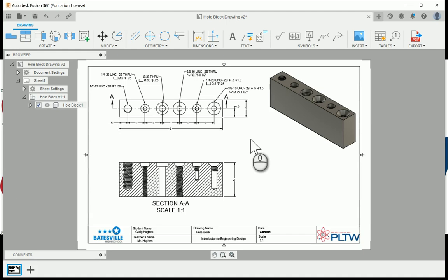In this video we're going to explore how to add tolerances to drawings in Fusion, and we're going to do that by utilizing activity 211 called Tolerate This. So on number 21 we have a list of tolerances we're going to add to some dimensions, and we're going to start off with letter A, which says that we're going to add a bilateral tolerance or a symmetric tolerance as noted in Fusion of 0.10 inches for the overall length, width, and depth.